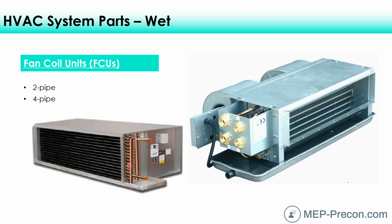However, on the heating side, for when it gets warmer in the spring, you could get a fan coil unit with electric heat in there. And that's kind of a compromise, I suppose. You're saving a bunch of the heating water piping, but you just have an electric coil in there. It's probably not quite as energy efficient as a gas boiler and all that, but it's going to be a little bit less expensive up front. So you could essentially have the equivalent of a 4-pipe fan coil in the springtime.